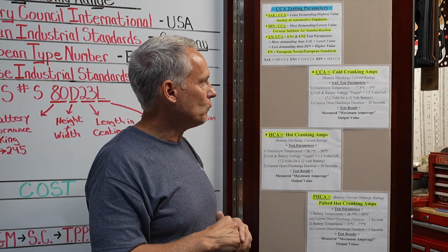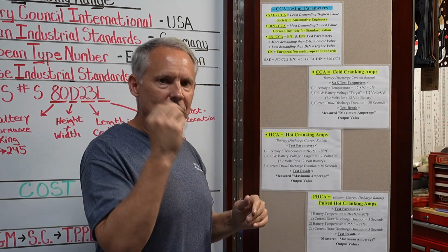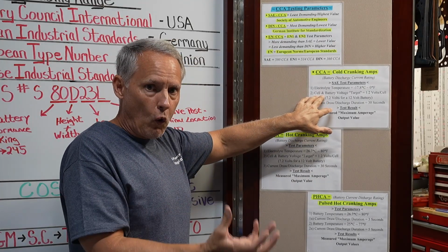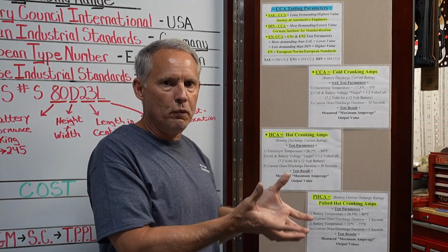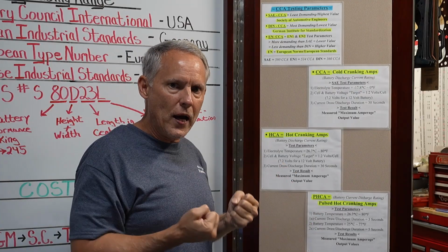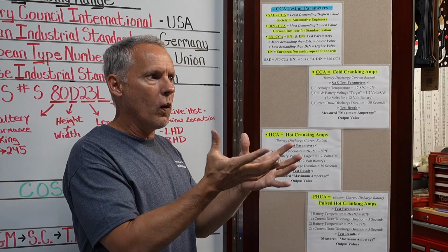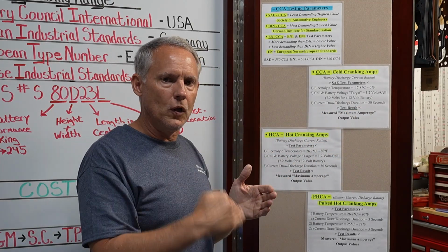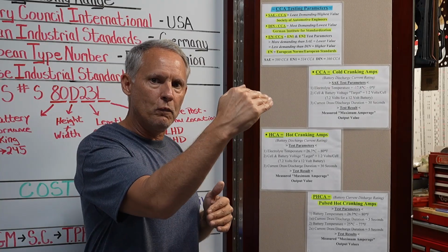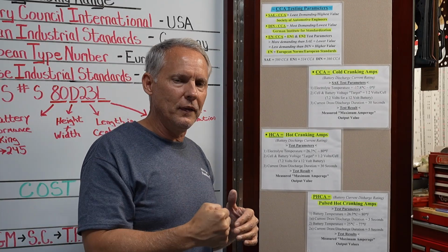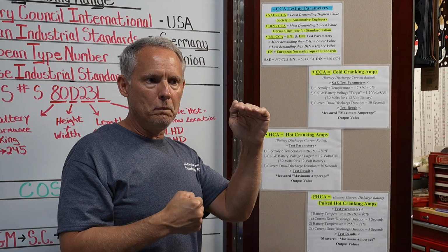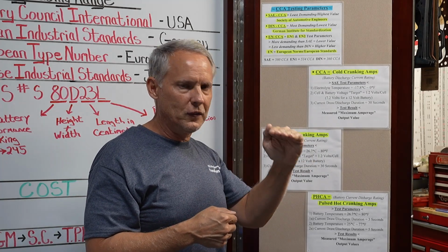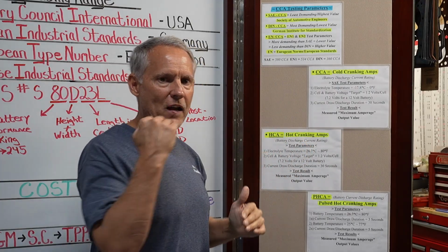And the electrolyte temperature is negative 17.8 degrees Celsius, 0 degrees Fahrenheit. So that's where we start the test. We're going to put as much amperage draw on the battery as it can withstand or provide, for a total of 30 seconds, not going below 7.2 volts, because that's our target. So we start at 12.8. We discharge the battery as rapidly as we can while not going beyond 7.2 volts, not 7.0, 6.8, but only to 7.2 volts, maintaining that for the 30-second duration.